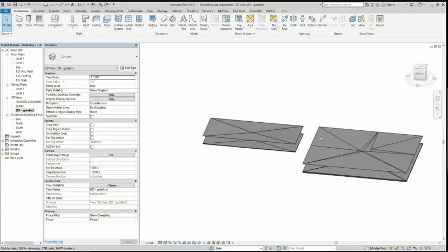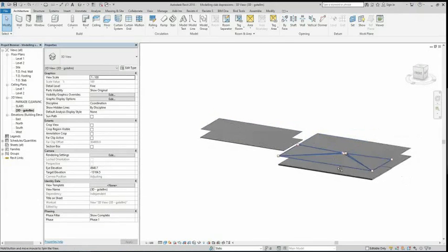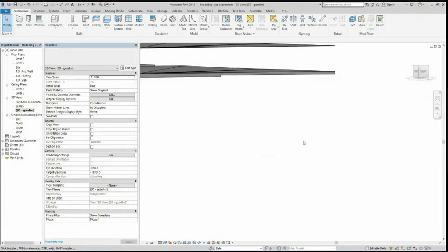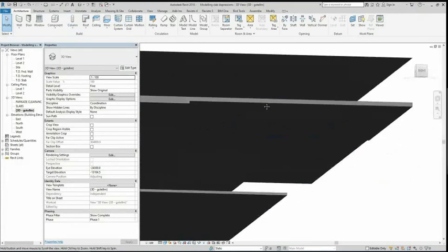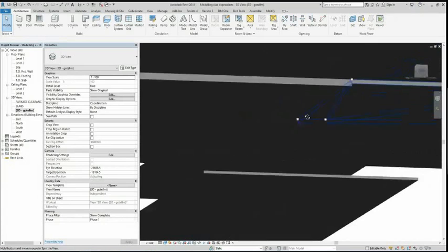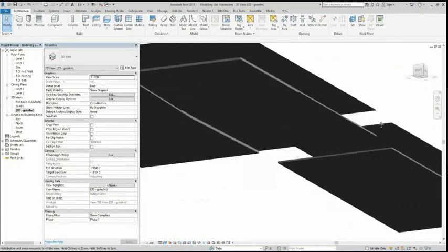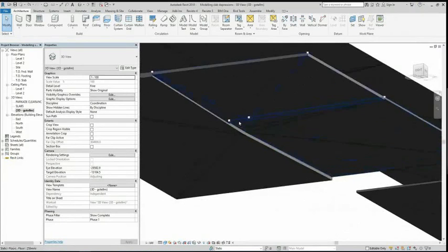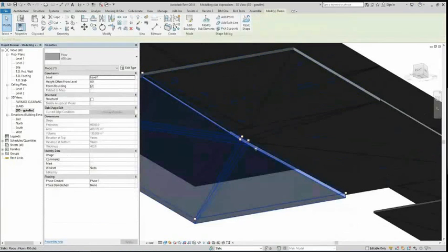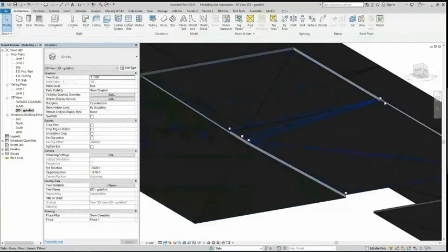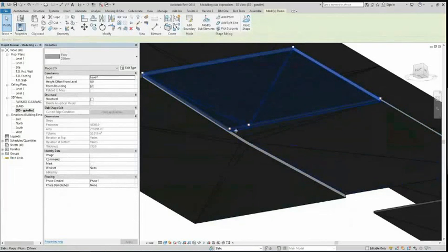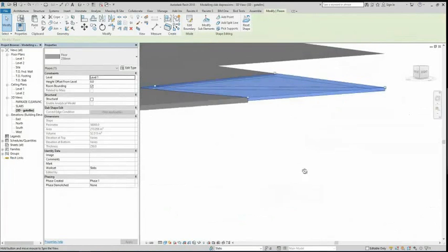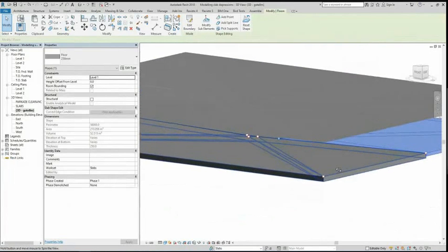And then additionally, I want to show this same sort of approach when you have a slab that has multiple thicknesses within the same footprint. So you can see here from a couple examples I have where I've modeled slabs that actually have 3 different thicknesses. So one is 400, one is 150, and one is 250 thick, and how you can model those 3 different slab elevations that fall within the same area drain footprint.